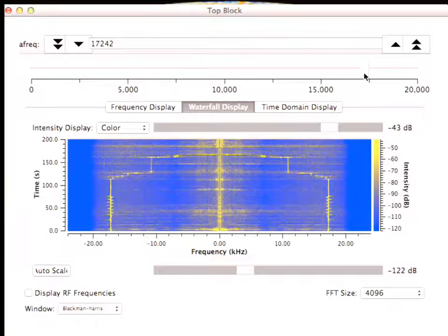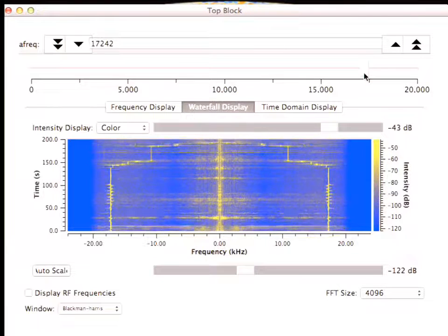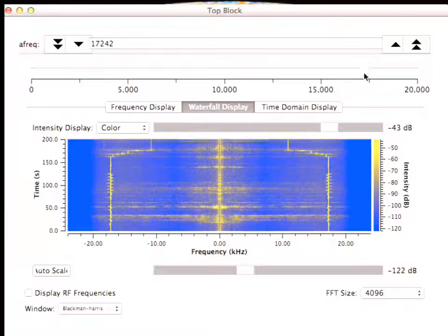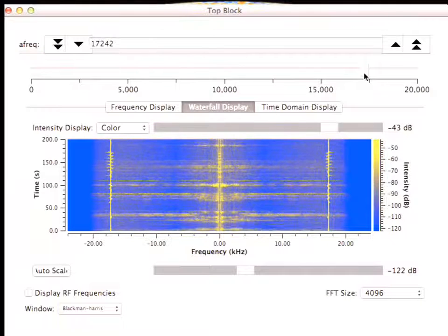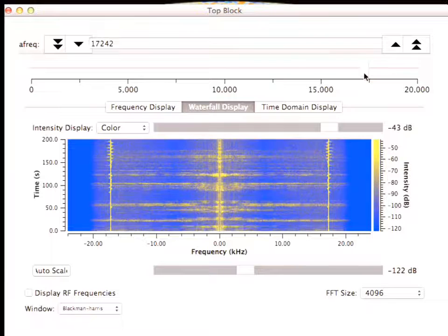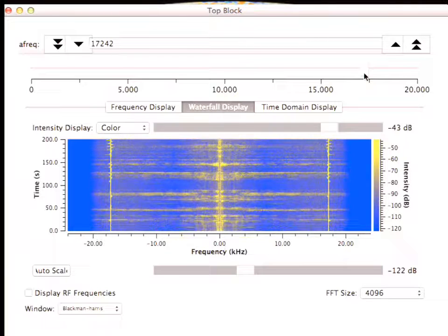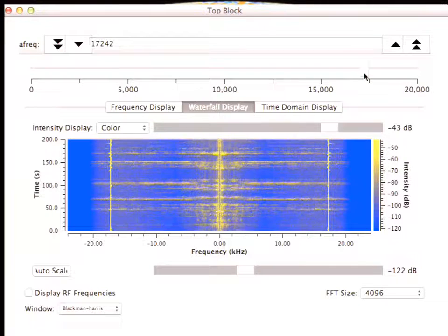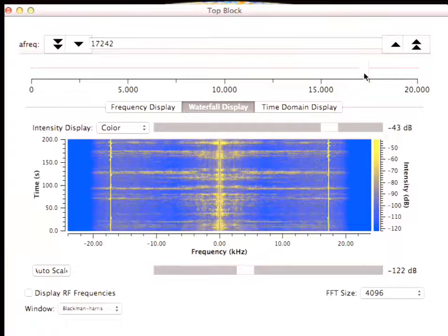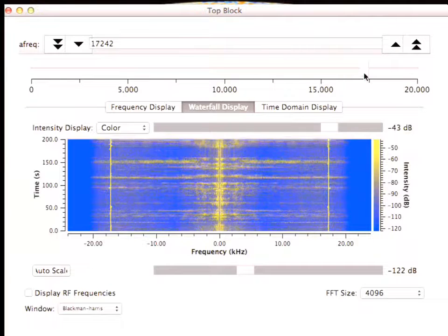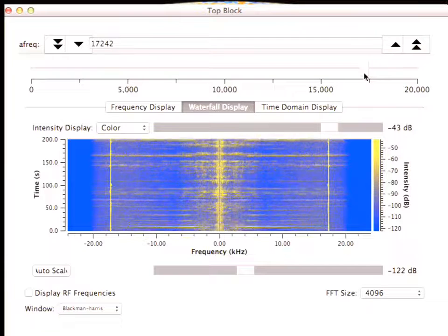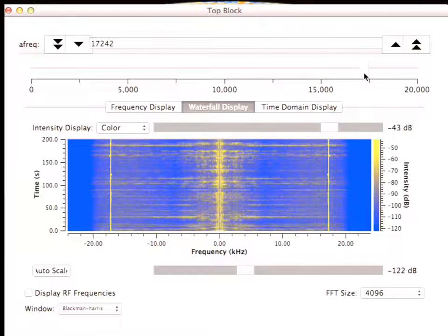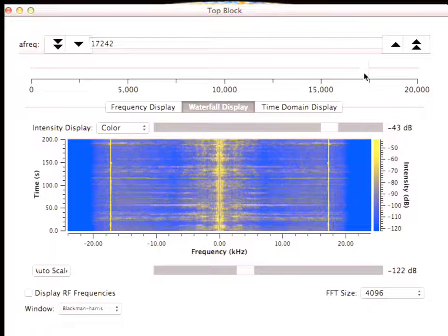So now, this is continuous wave radar. You send a continuous wave. It hits my hand and is reflected back into the microphone. Because I'm moving, it's Doppler shifted. And then if I put a filter in the receiver over this fundamental frequency, I will just see the reflections. Only stuff that's moving will receive a signal.